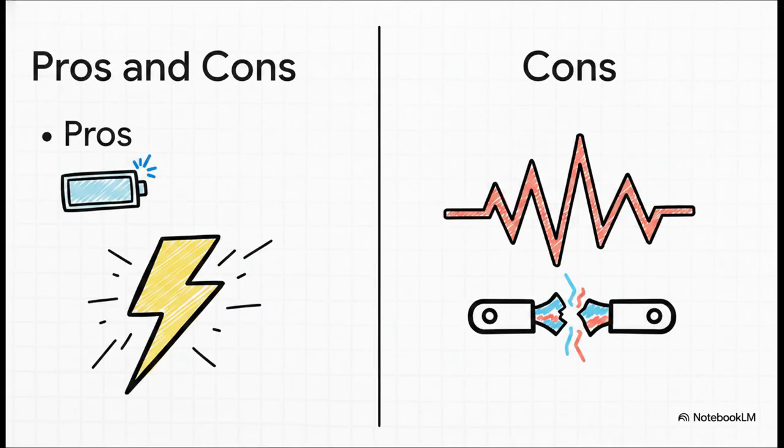Of course, in the real world, this unique behavior comes with some very distinct pros and cons. On the plus side, tunnel diodes are fantastic because they consume very low power, they're really inexpensive to make, and they provide extremely high-speed operation. I mean, remember, those electrons are punching through almost at the speed of light. But on the flip side, we do have to mention a couple of drawbacks. Those abrupt changes in load current with the applied voltage can be tricky to manage. Also, since it's just a simple two-terminal device, you don't really get proper isolation between your input and output terminals.